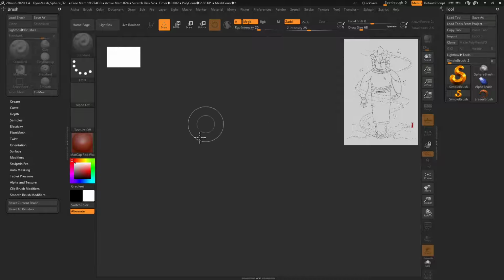Now, if you want to continue working on what you have here, you are going to have to disable the original functionality of the spotlight, because every time you bring in an image, you will use this image for sculpting or for texturing. By default it's on. So if you leave this as it is and you start working on a sphere or something, you start sculpting, you will see that you will not be able to do anything. It's because it's waiting for this image to be on top of this, so you can pass the information to the sculpt by doing it with add or subtract, or just with color as well if you want to. But we're going to disable that temporarily, so you are allowed to go back to work normally and then continue your work. And you only have this as a reference.